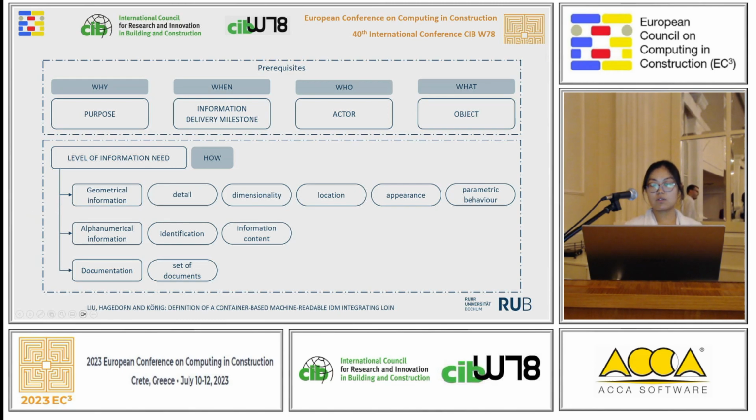The LOIN standard definition is considering the ISO standard 19650 part 1 for information management using BIM, and the information delivery manual IDM standard. To describe the correct level of required information for exchanging, the LOIN contains two parts for the information delivery. The first part contains contextual aspects of information.